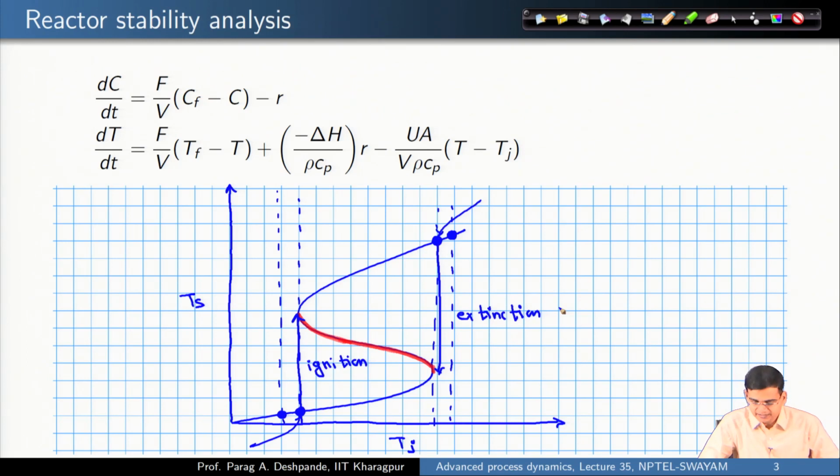And then what you will see is that this seemingly very simple system, which is a CSTR, you are stirring it, you are sending it a jacket fluid, and a very simple reaction A going to B, simply irreversible reaction, not very complex kinetics, first order kinetics, k C_A, gives this exotic behavior in the dynamics of your system.